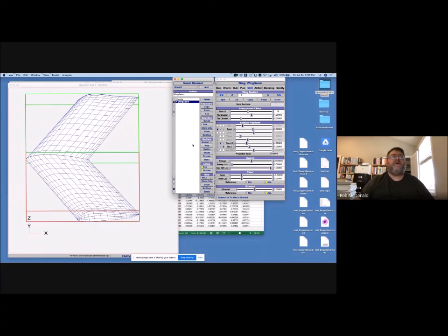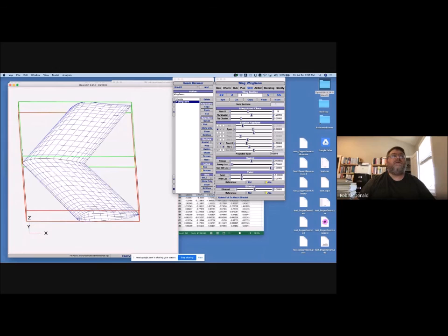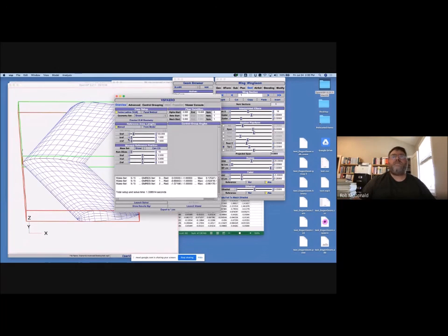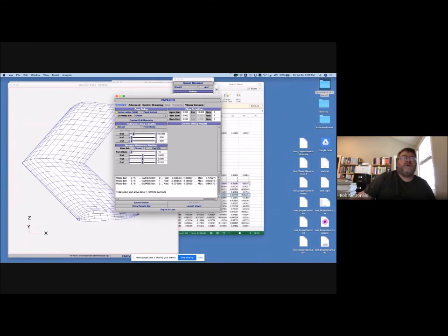Let me show you something very directly. When you're doing VSP Aero, there's this screen here where you can put the moment reference position, right? By default, it's just at 0, 0, 0, so it's at the nose. But that's not where the CG is. So if you're building up a model and you know where your CG is, by all means, just dial in this X and say, okay, I want my reference position wherever that is. For today, we're going to calculate where the CG is according to VSP. And it says it's 3 inches, or 3 units, back from the nose. And I think the chord was 4. So this fat airfoil out here at the tip is really throwing that off.